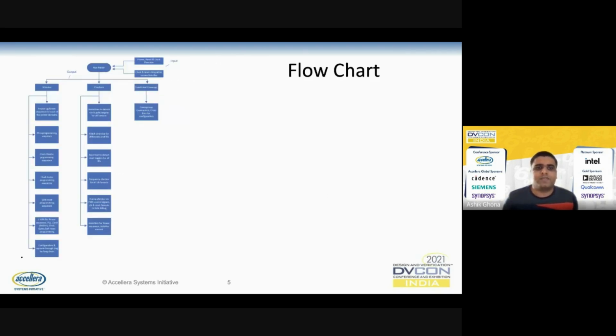This flow chart shows that the Perl parser takes these two specs as input and generates collaterals like stimulus, checkers, and functional coverage. Under stimulus, it generates the power up and down SV sequences for each gated power domain. It also generates the PLL, clock divider, clock gate, and soft reset related configurations. Basically, it generates sequences as well as constraints for this programming.